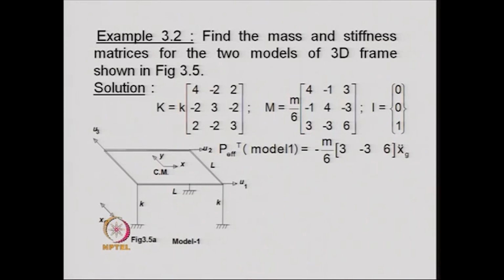Next, we take a problem of this type, in which we have 3 columns and a rigid floor. This is an asymmetric structure, therefore, it has some eccentricity, that is, the center of mass and the center of rigidity of the floor would have some eccentricity. So, this is an asymmetric system. Since it is a one-storied 3-dimensional frame, it has 3 independent degrees of freedom.